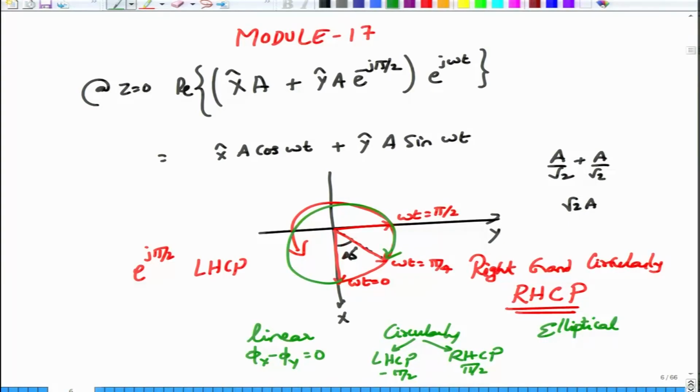In the elliptical polarization, you can still have the movement of the electric field vectors be either left or to the right, okay. However, they would not move along a circle, but they would actually move along the ellipse that you can see here, okay. So, they would actually be moving along the ellipse. Both kinds of ellipses are possible, left handed ellipse and the right handed ellipse. So, these are the different types of polarization of a uniform plane wave.